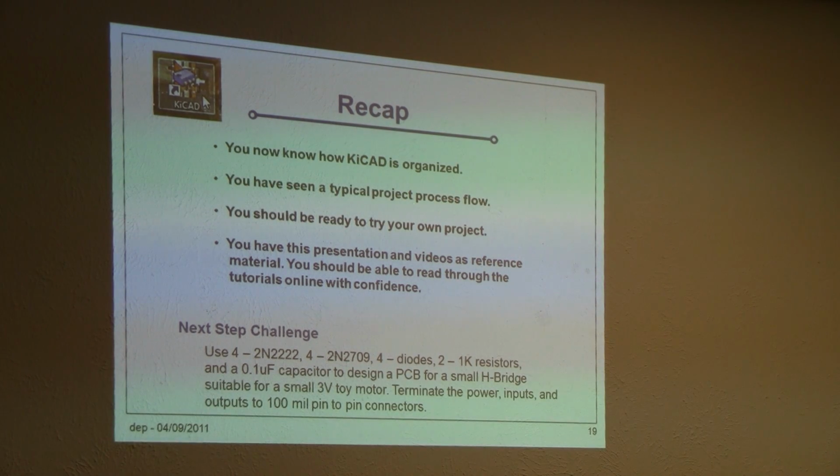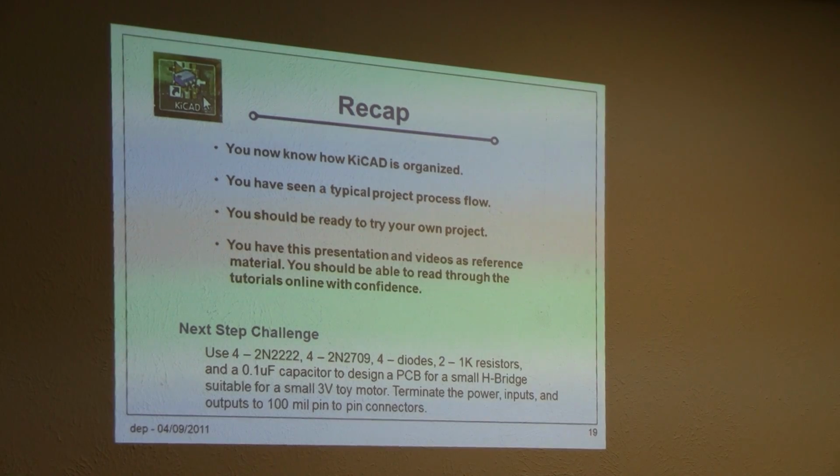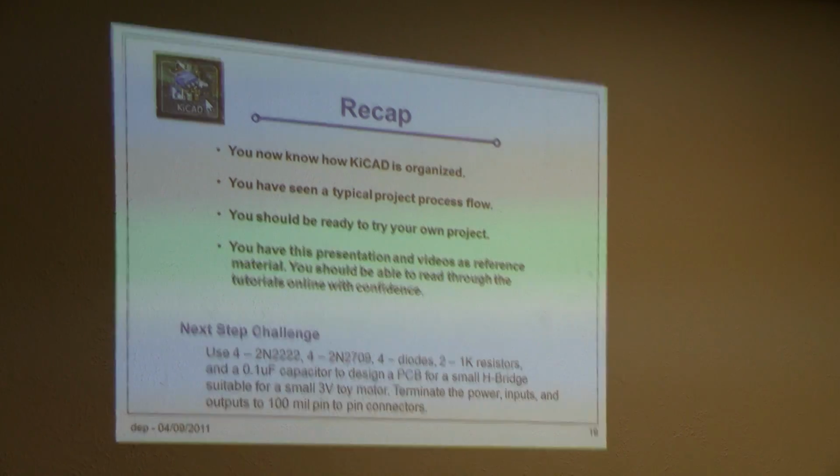Get yourself four 2N2222s, four 2N2907s, four diodes, probably 1N914s, two 1K resistors, and a 0.1 microfarad capacitor, non-polarized, and make yourself a little H bridge.